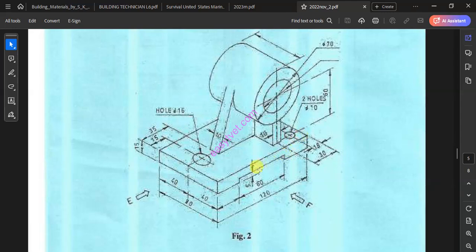So I'll start off from the front side by drawing this particular shape. Then I'll give it a 3D fill by giving it a press pull of 80. So I'll begin with this side. There is 15, this is 120, this is 15, and then the offset from the bottom edge, this hanging edge, is 5. So we'll start off with that one. Align one end, the other end, the distance of separation is 120.